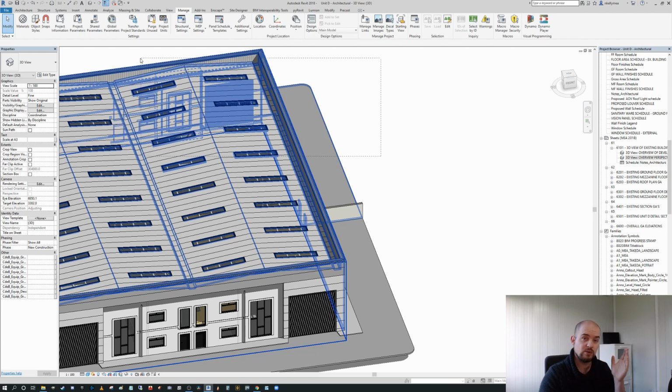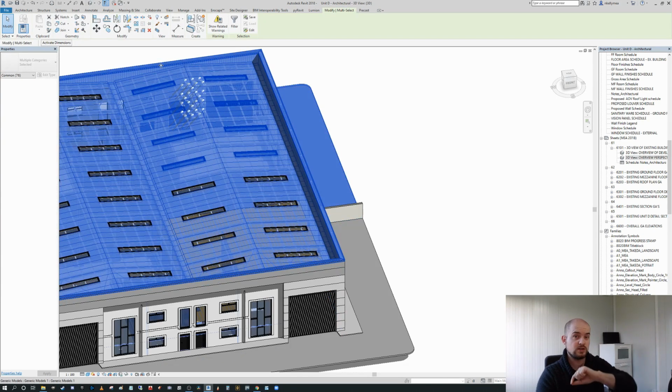So it's got to do with the nature of your project. It's got to do with how you want to control the visibility. But top left to bottom right only selects all the elements that are enclosed within the bounding box, and bottom right to top left, the reverse of it, when you get the dash line, selects everything that the bounding box actually touches. Okay, so that was step 2, how to use the directional drag selection objects in Revit.